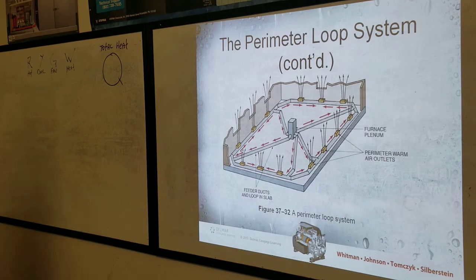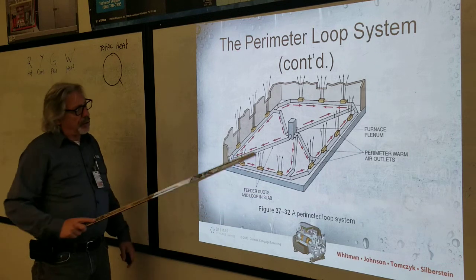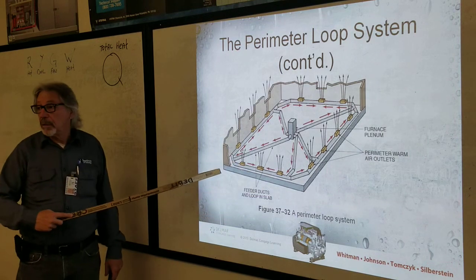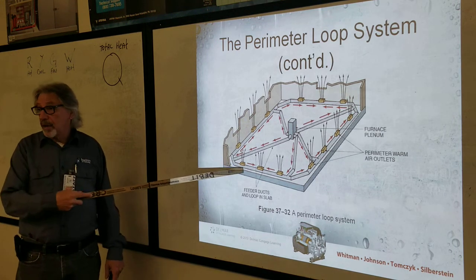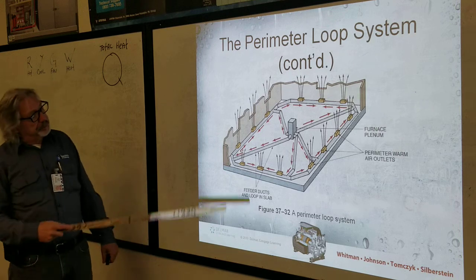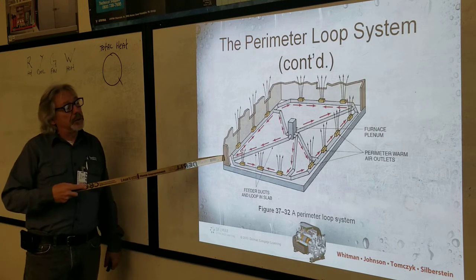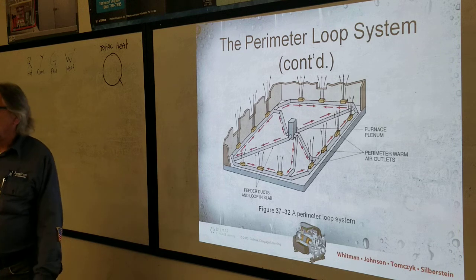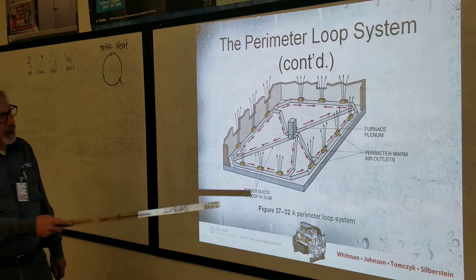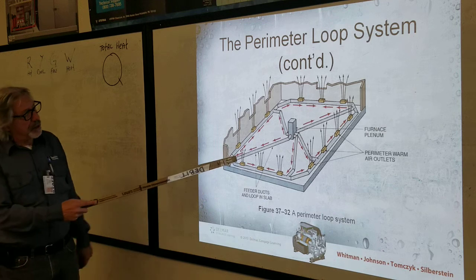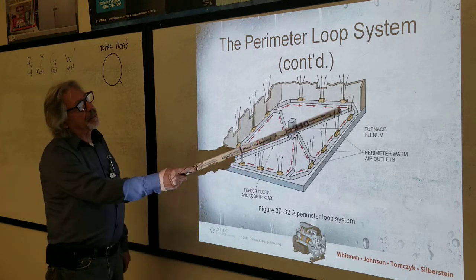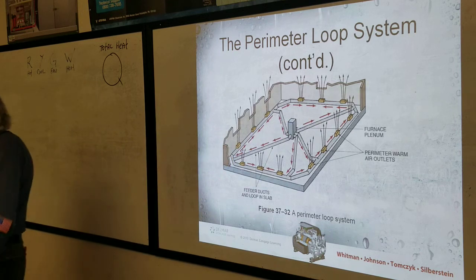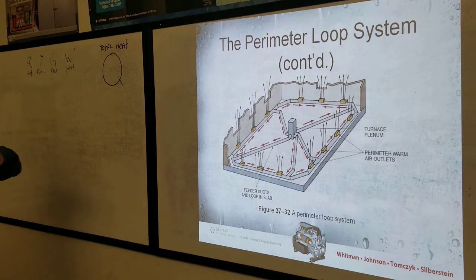So you got warm air going through there, and you can imagine if it snows, let's say, 5 feet of snow backed up on the side of this wall, the hot air is going to try and get to the cold, so you're going to have a big problem in the wall there. You can get drafts and stuff like that, because the heat's going to try and go through that wall. So once they keep the perimeter of that slab warm, that keeps the cold air from coming in through the slab.